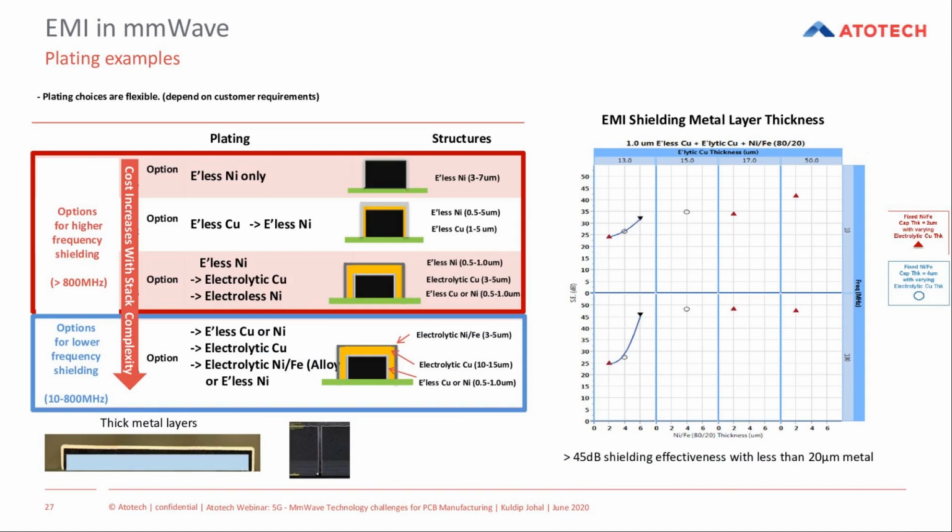So the table here shows you some of the, let's say, flavors of the metal stacks that Aditech has been testing. And we've done a lot of this testing with some key OEMs. And what we've done is there's two challenges that we had to obviously tackle. One key challenge was developing a process to metallize the outer mold compound. And that was where we needed to meet the OEM requirements from an adhesion point of view.